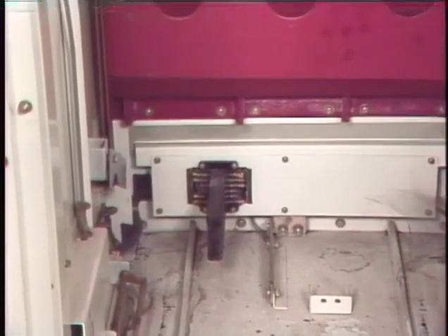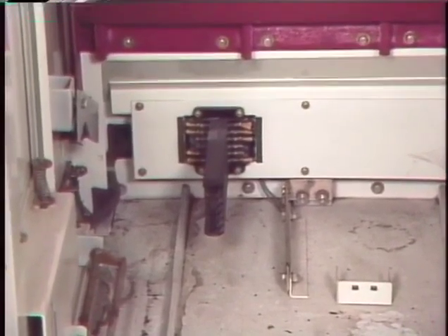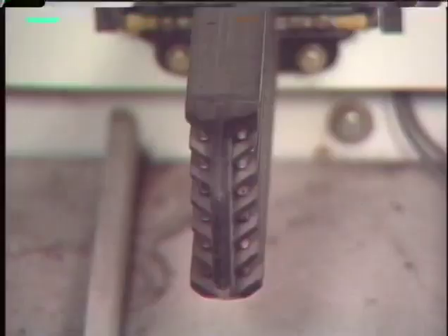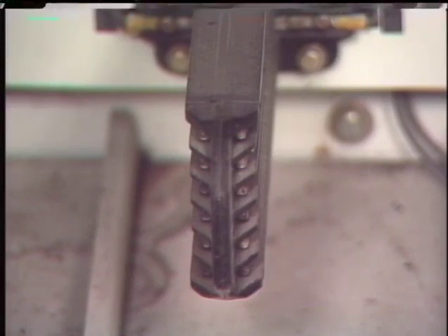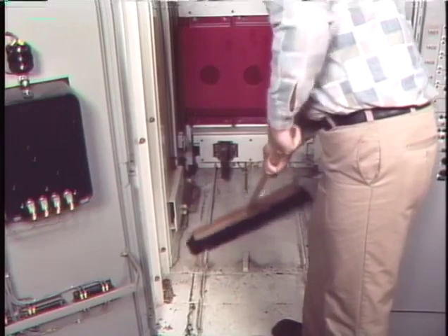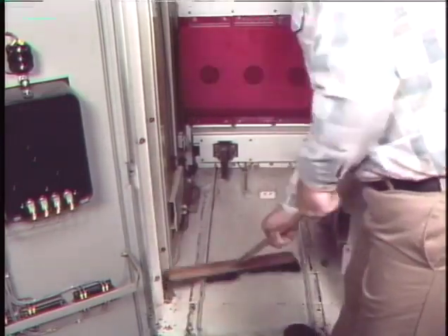The connections for breaker control power are also checked for loose, broken, or missing parts, chips, cracks, or corrosion. They should be checked to make sure the connections are not bent or twisted out of shape so that they align properly with the connections on the breaker. It's also a good practice to clean the interior of the cabinet. Otherwise, dust and dirt can accumulate on moving breaker parts and cause them to bind.